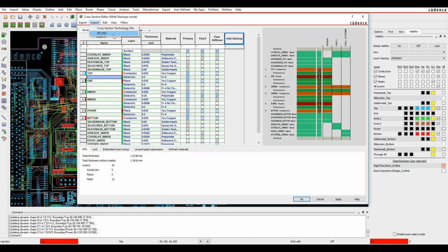If your PCB fabricators are using Polar, a tool many fabricators use to define things like the impedance for a specific cross section of the boards, they can export an IPC 2581 file, which you can then import directly and use that information. So you haven't got to set this up yourself. You can use the information directly from the fabricator.